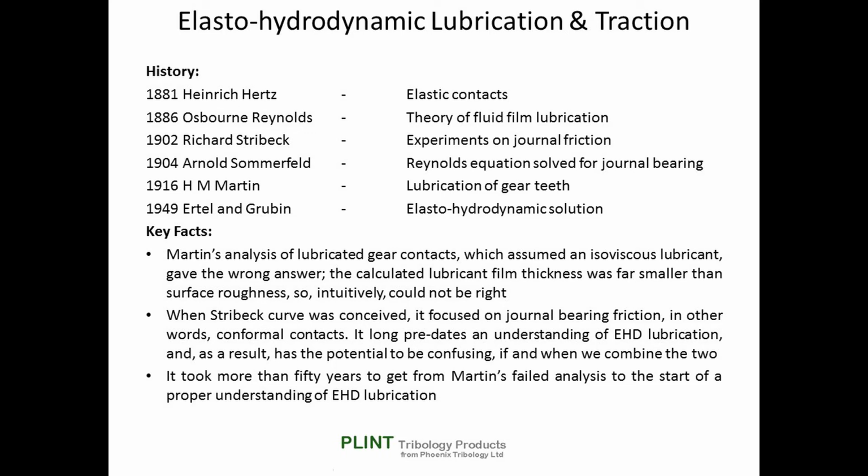There is one key fact to note, which is that H.M. Martin's analysis of lubricated gear contacts, which assumed an iso-viscous lubricant, gave the wrong answer. The calculated lubricant film thickness was far smaller than the surface roughness, so intuitively could not be right.